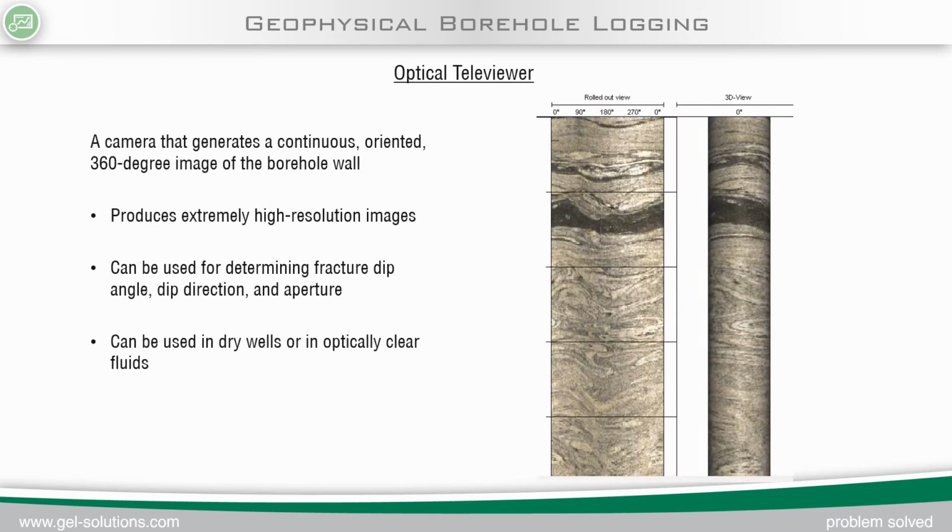Next is the optical televiewer. This is a camera that can produce a continuous and oriented 360-degree image of the borehole wall. These are high-resolution images that can be used to determine fracture dip angle, dip direction, and aperture. This tool can be used in dry or clear fluid-filled holes.